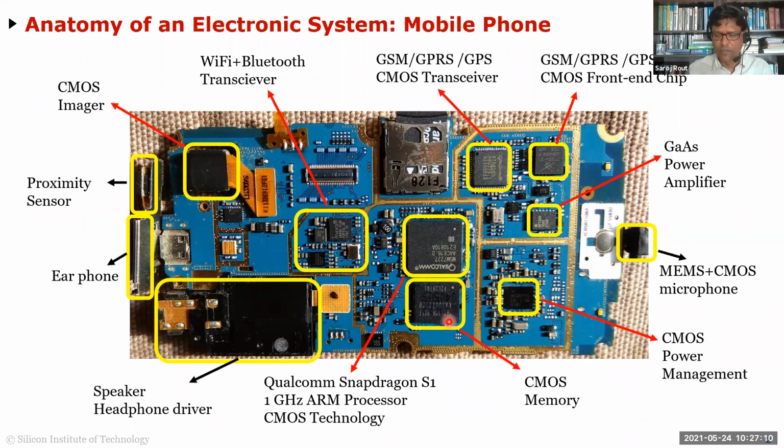And typically all these phones have what's called a power management chip. That's essentially because you have one battery. Typically it's 5 volts or 12, some of them carry 12-volt batteries right now, but most are in the range of 3 to 5 volts. So it's a lithium-ion battery, but all these chips have different requirements. For example, this is probably running on 0.9 or 1.8 volts, and this is probably running on 0.8. So all the high switching ones are running on really low voltages.